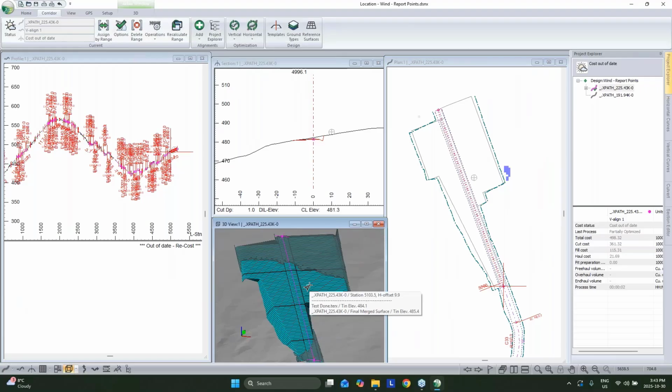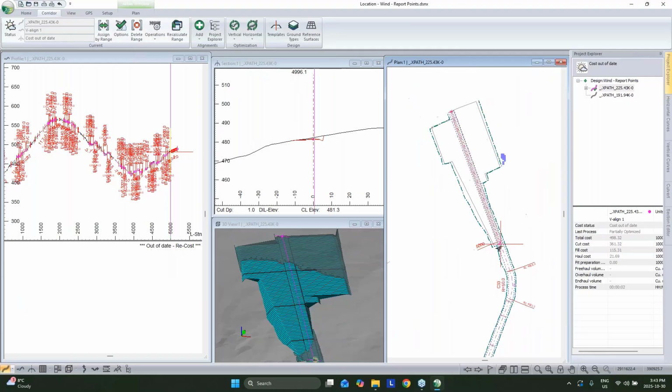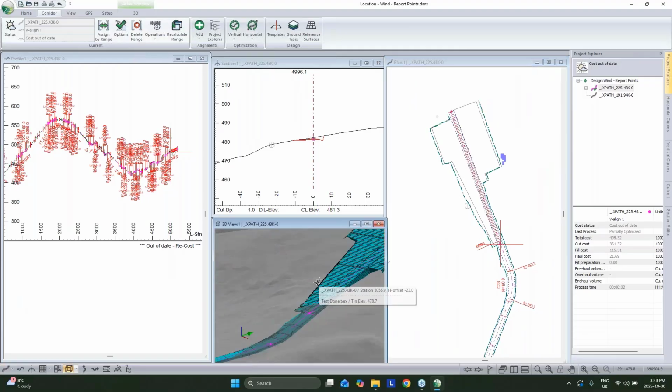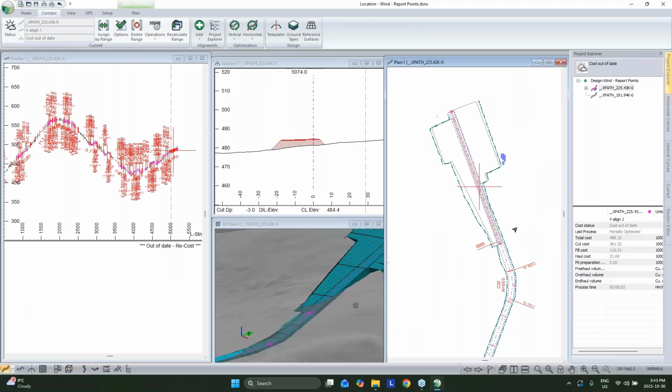It's kind of at the heart of a cross-section model. Well, centerline is important, your cross-section geometry is important, but of course where that cross-section geometry is being calculated is important, and hence Aaron's emphasis on it. It's kind of boring, report points, but it matters. So it will probably help you in the future if you're trying to capture a detail that's otherwise difficult to capture. With that, I'll pass it back to Aaron.